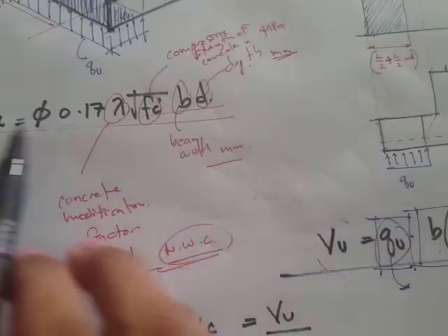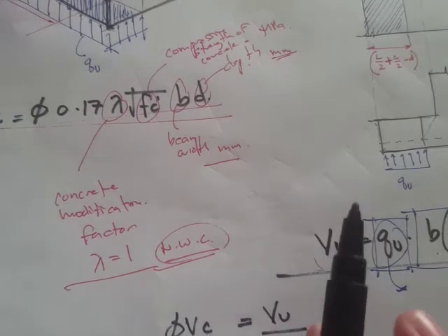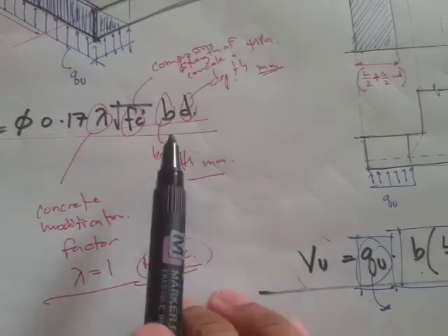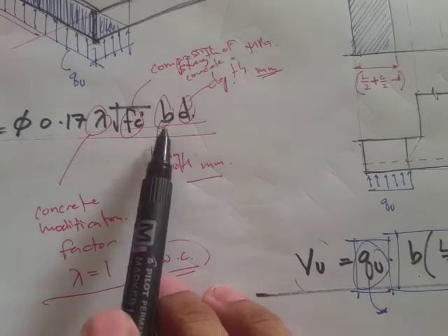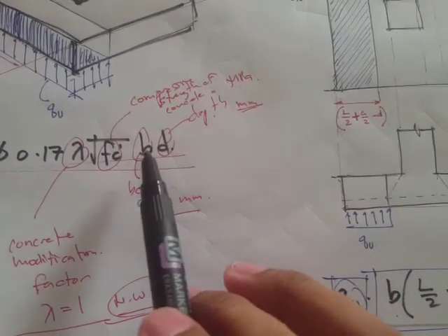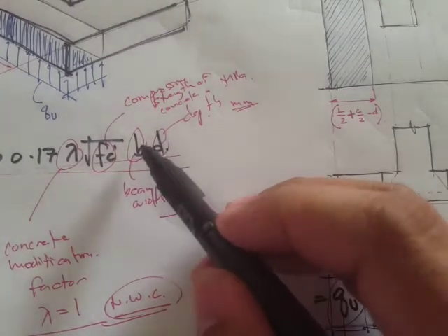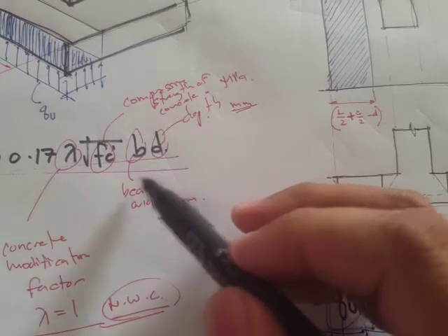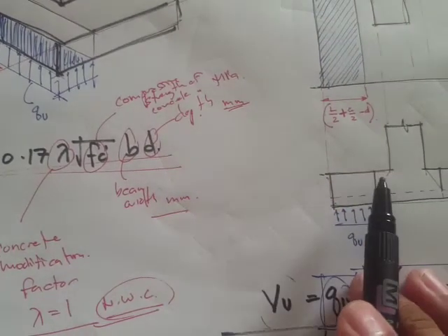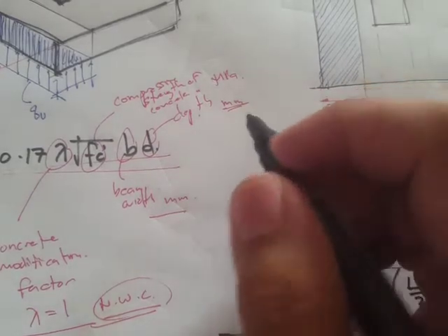Okay, so the same goes through here. Just a couple of notes when you are computing for this, just make sure that this one is in mm, because at first you might be using the units in meters for the beam width, since our given pressures are in kilopascals.